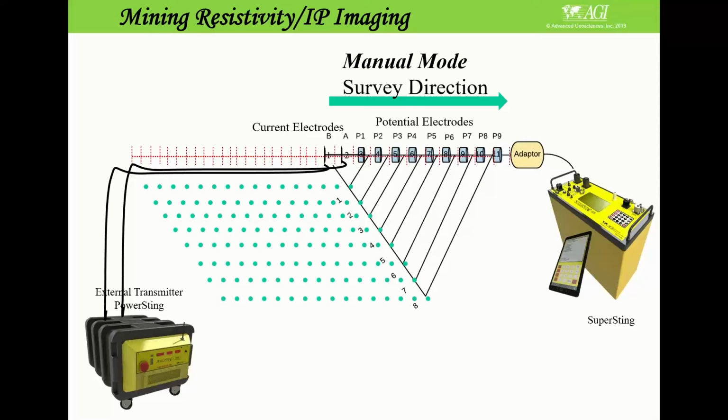In this case, if you have some fractures in the mineralization zone coming through as thin layers, or fracturing where the mineralization is less than 25 meters or 50 meters, you will not find it because of the large electrode spacing. So that's the limitation of this one.